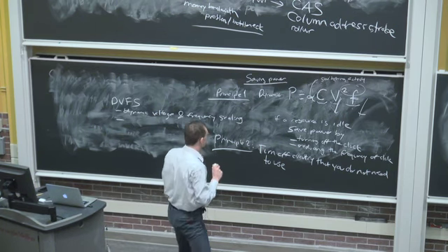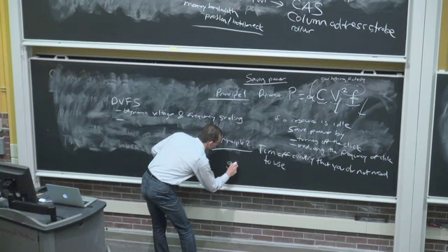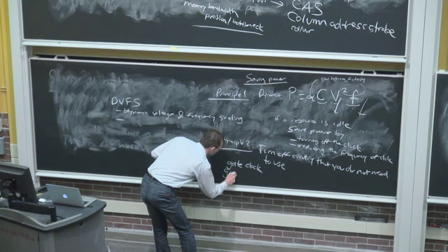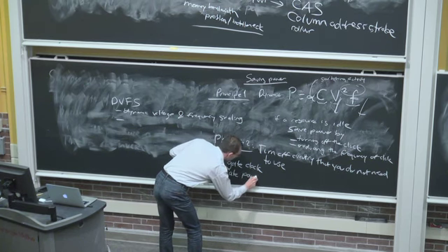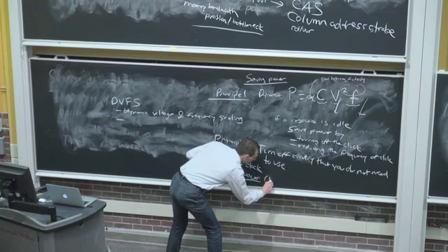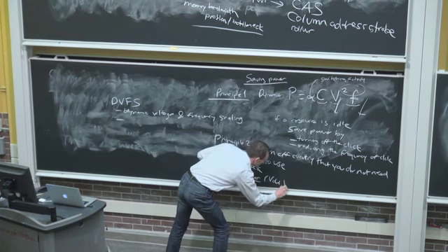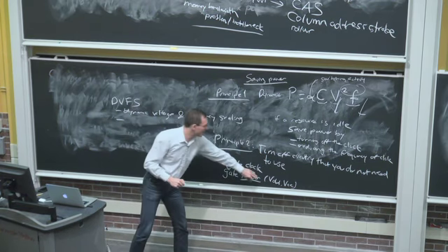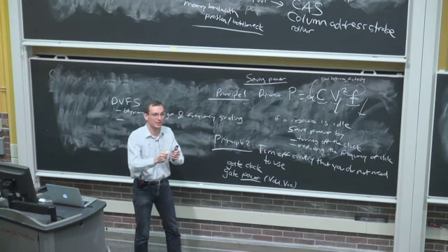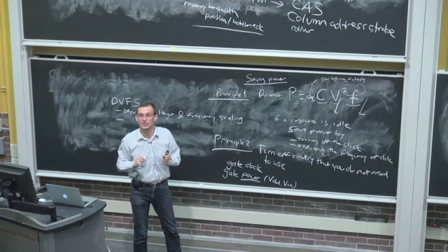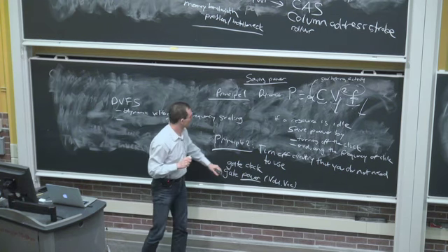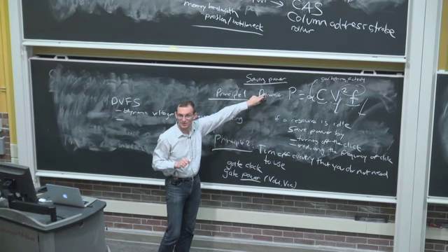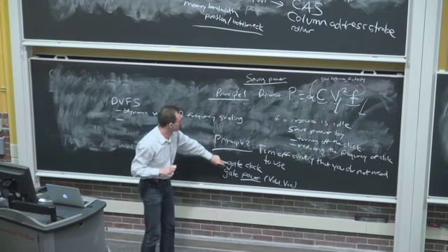Basically, there are ways to gate the clock and gate the power. These are actually power lines, the VDD or VCC, depending on what course you've taken. You can actually gate these lines such that the circuit doesn't leak. It doesn't consume static power. So this was the dynamic power equation. You can gate the clock to reduce the dynamic power.